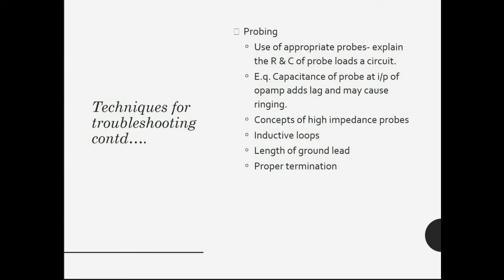Not only is the input resistance very high, but more importantly, the input capacitance is very low, with the capacitance normally providing the limiting factor. The reduction in the capacitance enables sensitive waveforms to be measured more accurately.